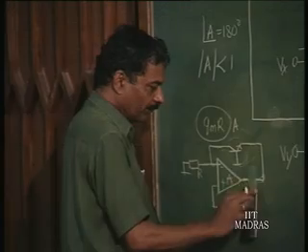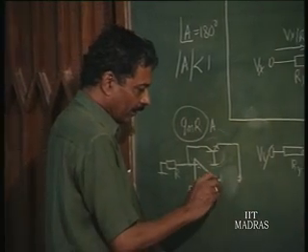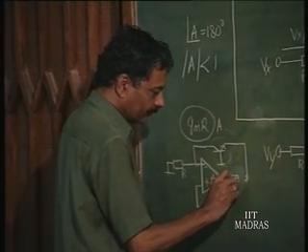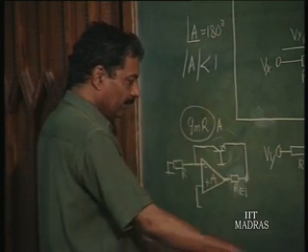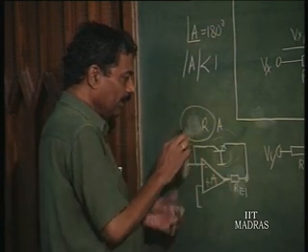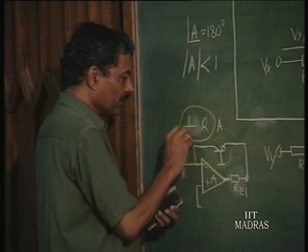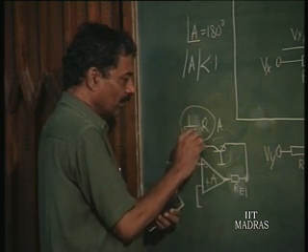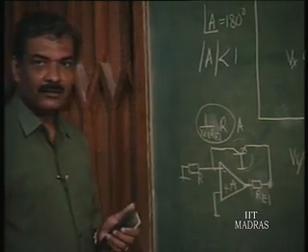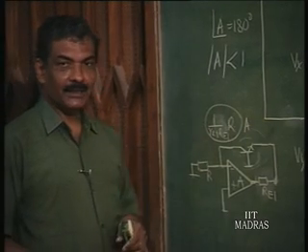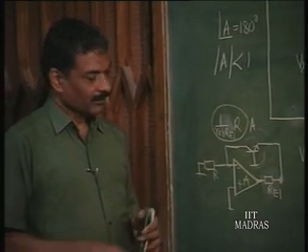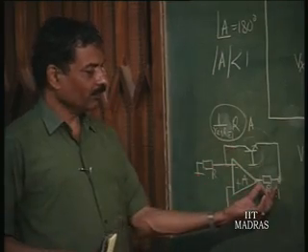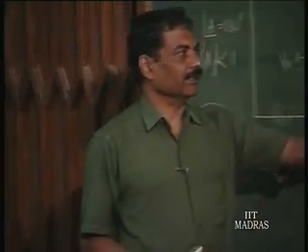Gm is reduced by putting a resistance in series with re, let us say Re1. So, this Gm, instead of 1 over small re, it will be 1 over small re plus Re1. So, that R over Re1 is less than 1. So, that is the idea for putting a resistance in series here.